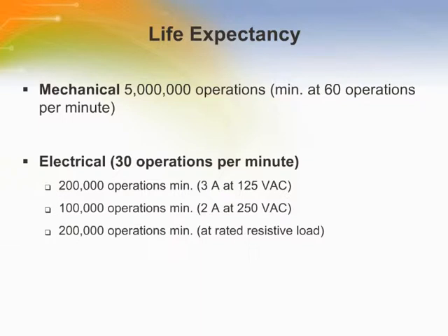The life expectancy of a D2SW switch is presented by electrical life and mechanical life. The electrical life means the duration in which the normal switching operation is performed under the rated load, as long as the switch is used with the rated over travel. The mechanical life indicates the duration in which the normal switch operation is performed without the contacts energized, as long as the switch is used with the over travel. The value listed on the datasheet is not guaranteed, it is just a reference value.